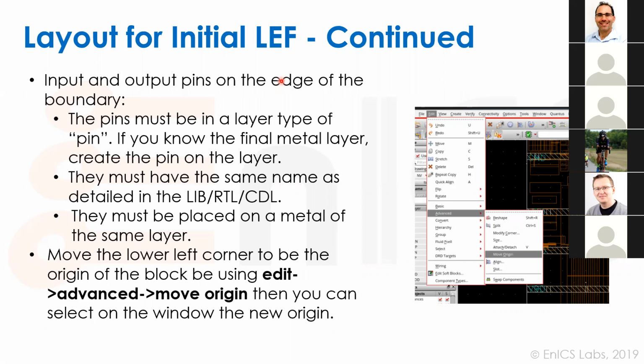So here we're talking about SRAMs or other blocks, and these blocks, if you put the pins not on the boundary, it's not good for the router. The router doesn't like it, and it will often cause all kinds of problems that you don't want to deal with. You're talking about macros. But I will say that power pins should be fully extracted, so they should be on the internals as well. Correct, Slava? No, it could be, but it's too much.